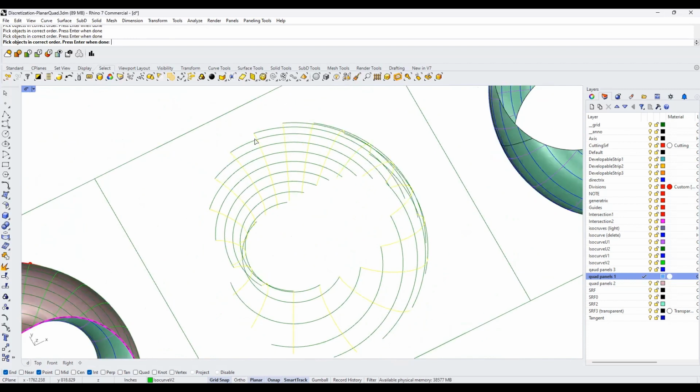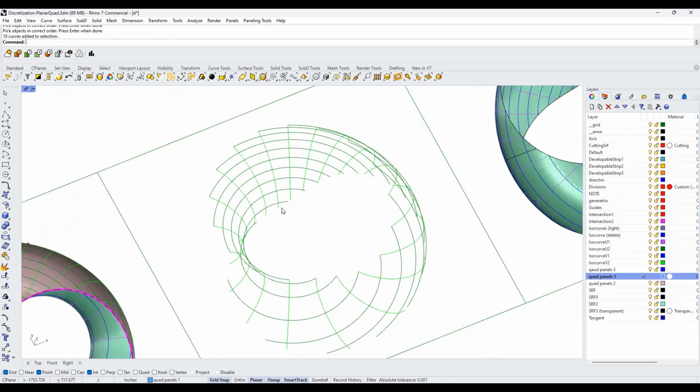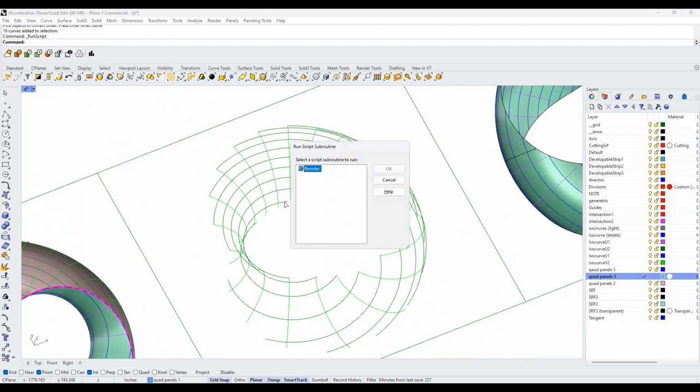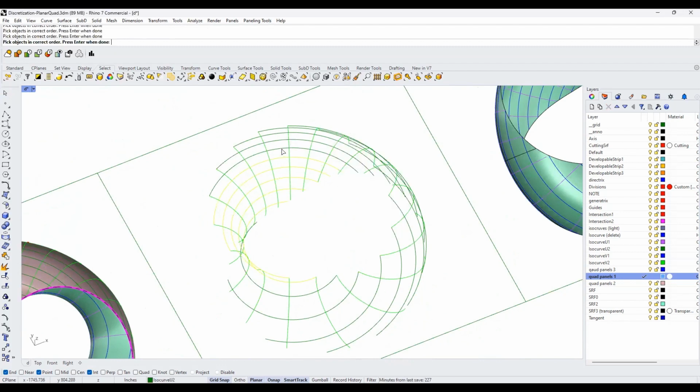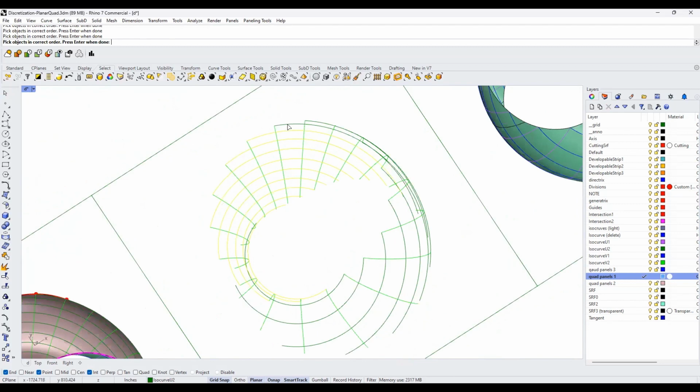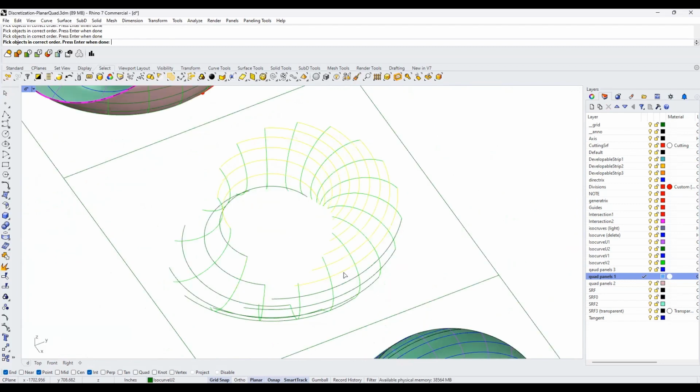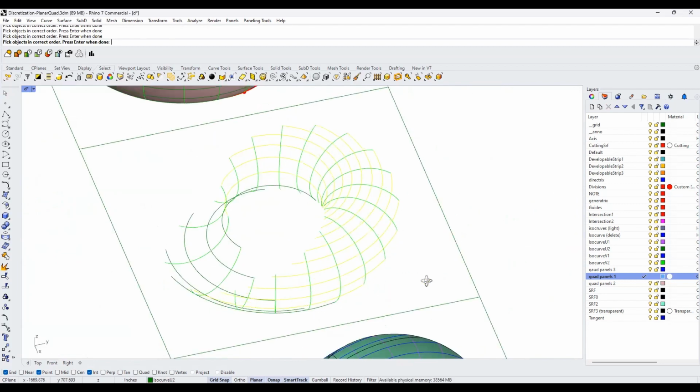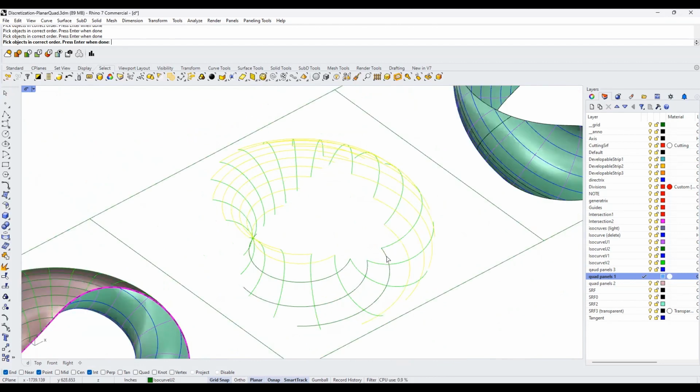And when you hit finish, you hit enter, and then you have to wait for it to finish. Those are now grouped and ordered. And then you've got to do the other one, in the other direction. The reason this is important is because Rhino, in its memory, groups curves or anything in the order that it was created.